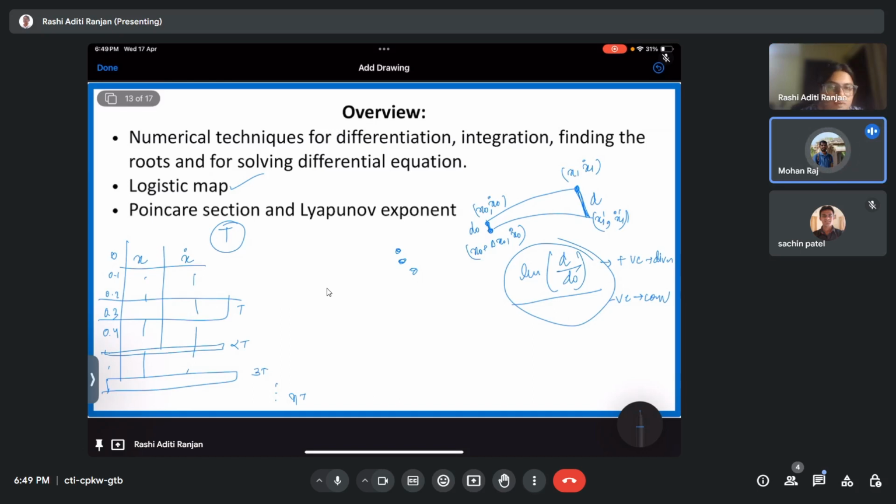Yeah, we are using an anti-aliasing filter or low pass filter for removing frequencies above a certain frequency, but below that frequency definitely some noise will be there. Yes. And apart from that, it may happen that you'll have noise at a higher frequency also. You can have noise at a lower frequency also. That is why you use windowing of the function. However, you are absolutely correct that with noise, there are many cases when our system response is actually periodic, but because of the noise, my system behaves chaotically, and people are not able to identify whether it is periodic or chaotic.